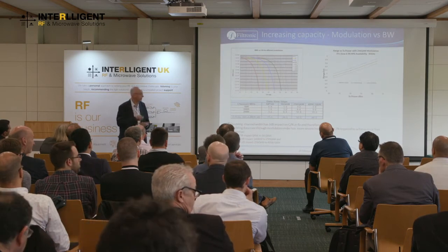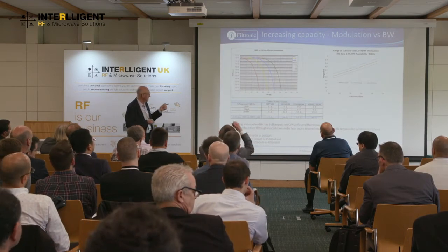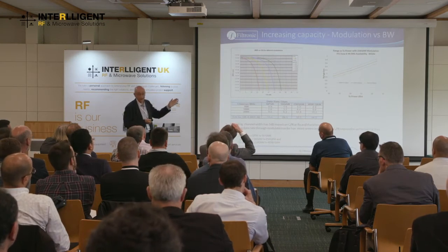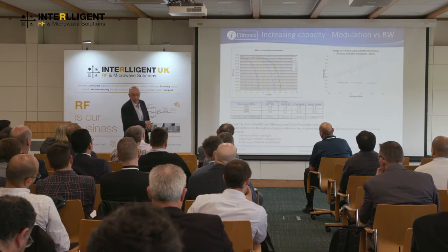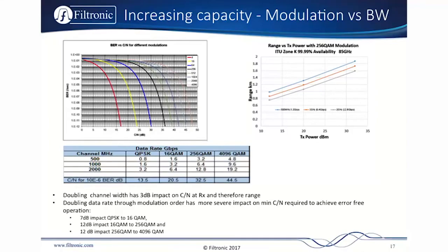This is all coming out of the link budget. So increasing modulation order, people talk about going up to 4K modulation, but you can see that you're going to have to increase the carrier to noise ratio dramatically for that to work.